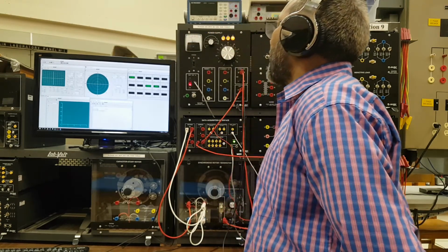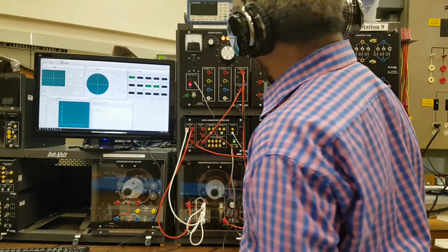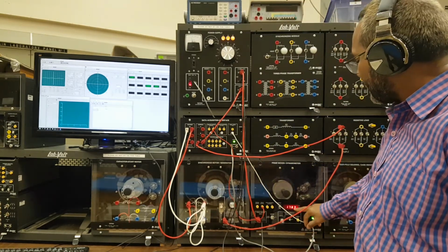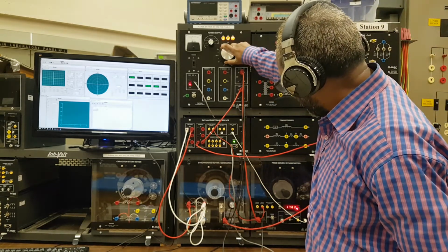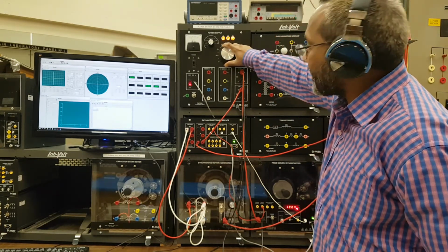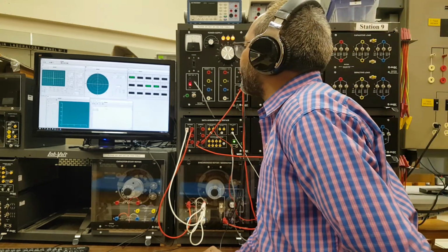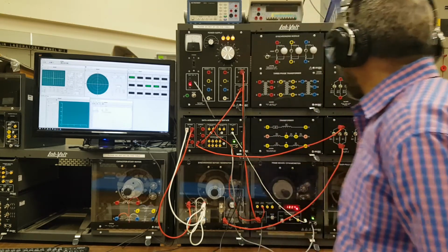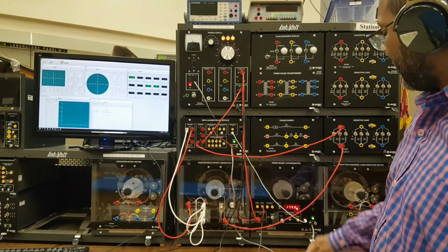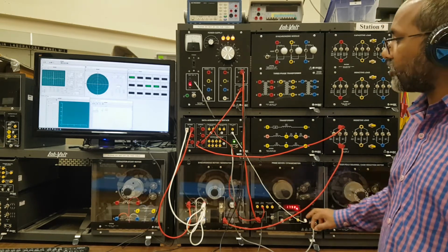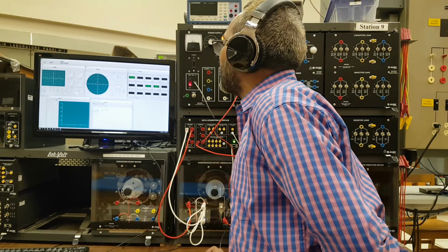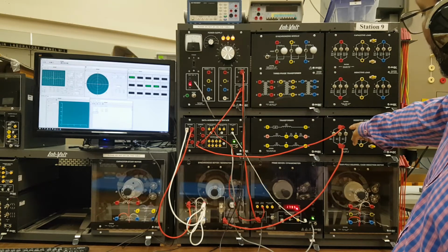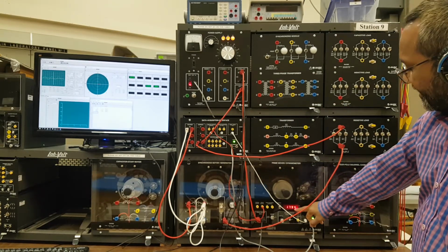Okay, and then we'll try to maintain the speed. So we just add the resistance there, and see the speed is changing a little bit. So I will just adjust it to 1800 RPM, and then I'll take the recording there. So basically the field current is changing here. So I will take the next one and check the speed, not much change. So I will just take the reading there. And the next one is this one, and the speed is a little bit changed.